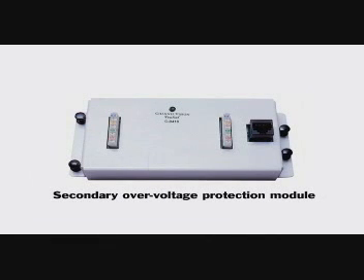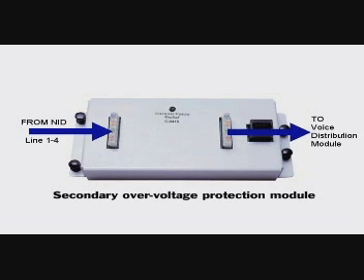A good example is this Channel Vision surge protection module. It provides secondary overvoltage protection on 4 incoming voice lines and is connected between the NID and the voice distribution module in the distribution center.